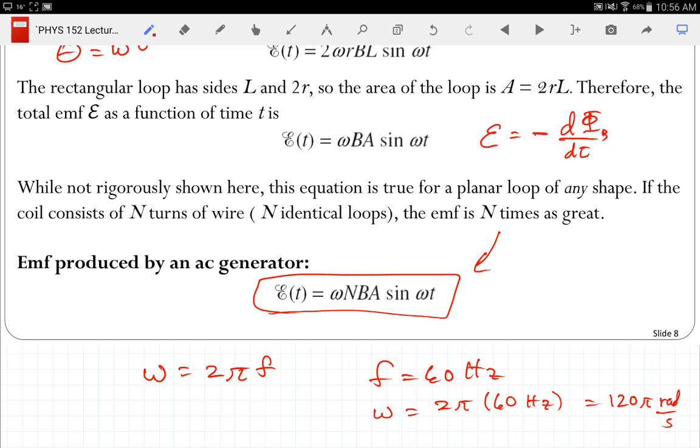Now, their moving water was only dropping a reasonably small amount, and when you suddenly have a big change in the load, it would slow the wheel down because the water just couldn't keep up. And so the frequency would drop when the refrigerator turned on. But then it would catch back up. Then somebody else's refrigerator turns on and does the same thing.